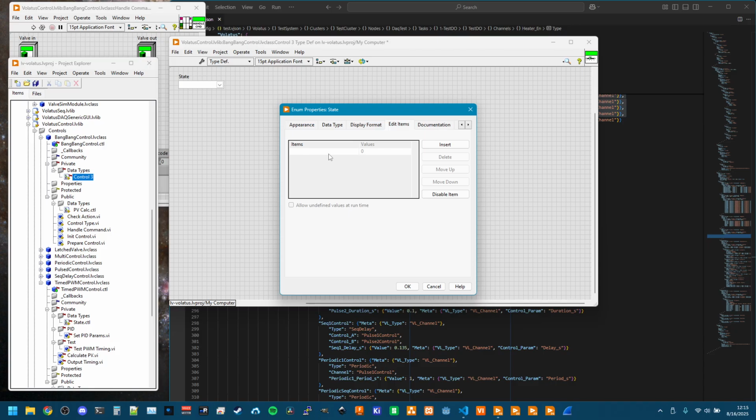So let's do that. Always start off with an idle state with these. Well, not always, but so far, I've always started out with an idle state. I'm going to go into a start state. So anytime we receive a command to turn on, we'll transition into this start state. And that will let us see if we should be ramping up or ramping down, or if we're already in the middle of the range, maybe do nothing.